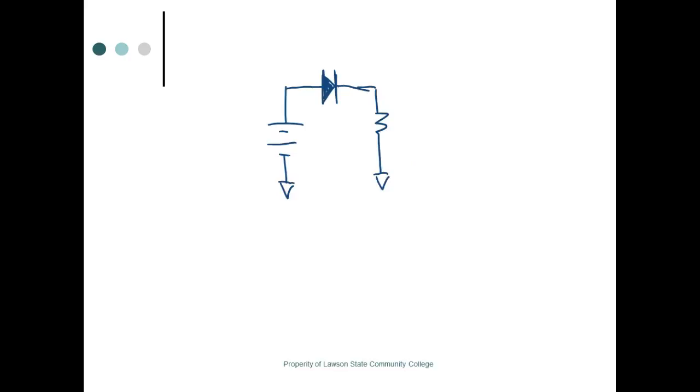So that means when I make my measurements with my voltmeter, I'm going to put my black lead on the common. And then I'm going to come over here and measure right there. Well, let's say this was plus 12 volts. All I'm doing is measuring across the source.